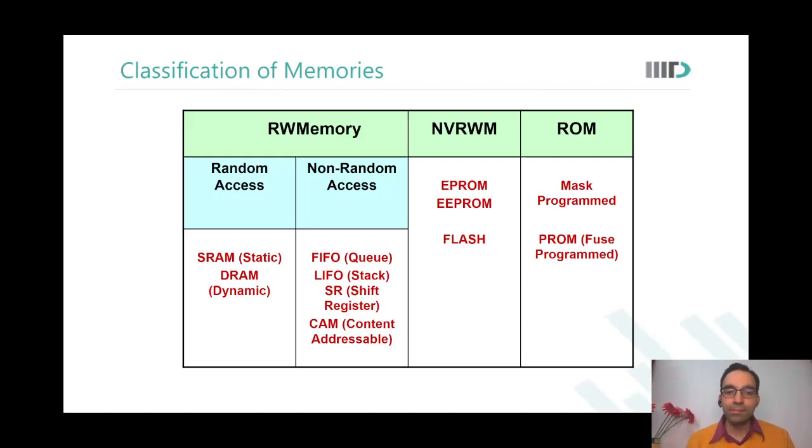So after I have fabricated a particular lot, then I'm doing a kind of initial step to make it operable. After fabrication has happened, I estimate what lot the device is at. Yes, sir. Now I simply fix that if it is a fast lot, then the leakage is going to be very high, so I have to lower the voltage of operation so that leakage comes under control. Because it's already fast, performance is not an issue for me. So I will trim. Instead of operating at 1.3 volts, operate the chip at 1.26 volts.